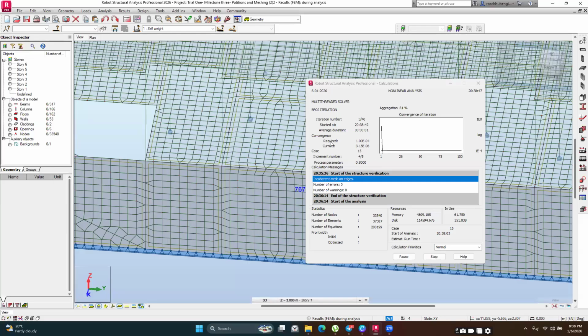Then the other error that you may get at this point is the isolated node, and members not aligned to any story. Those are other two errors that you may assume because they do not impact the structural analysis. Even if, say, a beam has not been assigned the same story, the load takedown is going to follow the right paths. If you have isolated nodes, you could delete them. But if you are already doing your analysis, you could just let it run through. They're not going to affect the quality of your results.